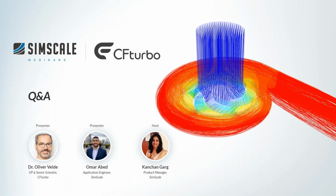The roughness of your surfaces can be defined using a surface roughness parameter. In the CFD context, these models are based on experimental data collection. So if you're working with a surface roughness of 0.5 millimeter, for example, what that is actually modeling within the CFD context is similar studies of essentially beaded elements that have that thickness side by side for that roughness scale.